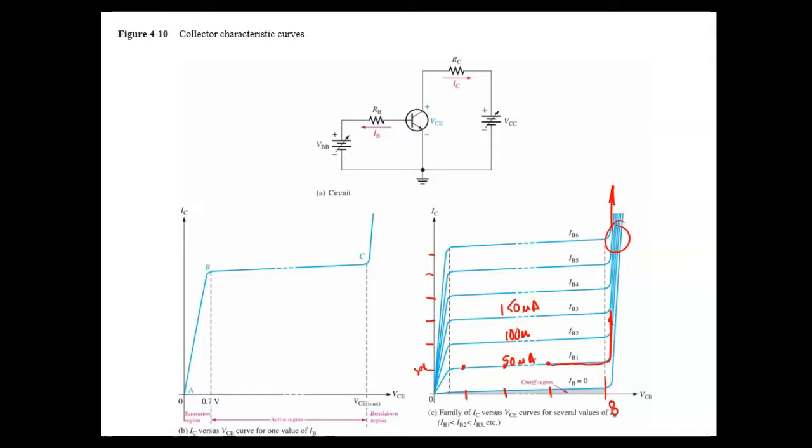But it's not exact, right? You understand that? So your curve should have a slight slant until you get to 8 volts voltage collector to emitter, and we've exceeded what the transistor would do. Now, of course, we had to turn it off real fast because we saw that the transistor was conducting, producing almost 900 milliwatts of power, right? So I cut it off real fast.